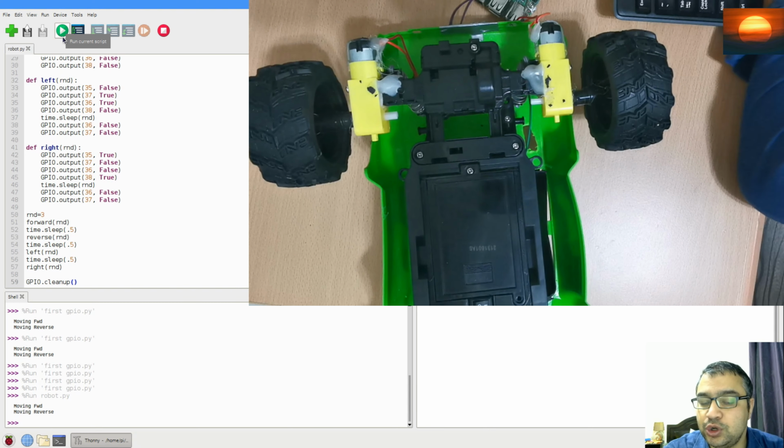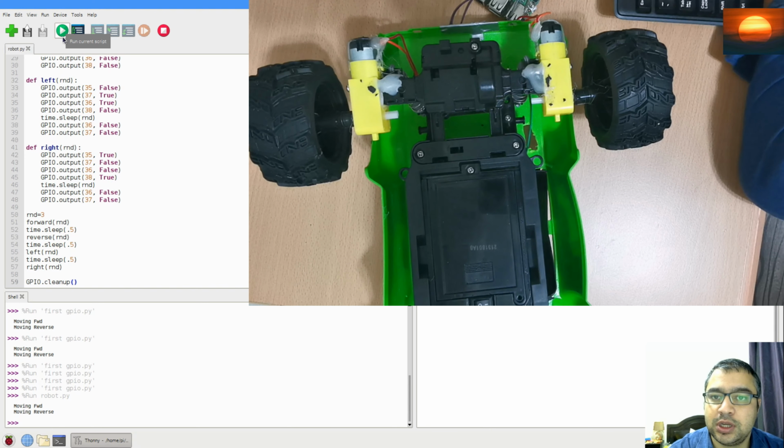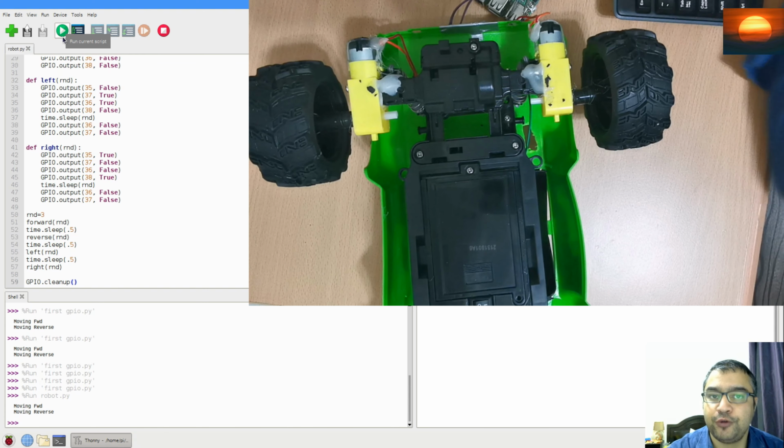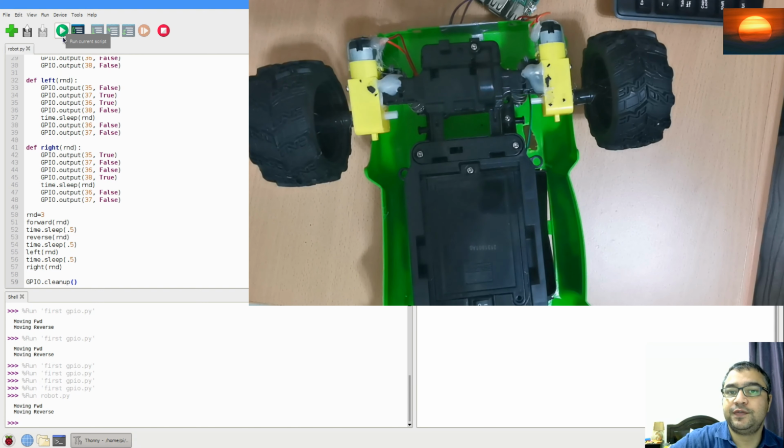Now what we need to do is take an input from our ultrasonic sensor, which we are going to place in front of our vehicle. One is going to be on the right and one on the left. We will place our ultrasonic sensors on our motor so that it will judge the distance based on that sensor and take the decision based on that.